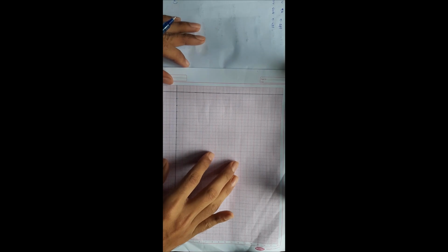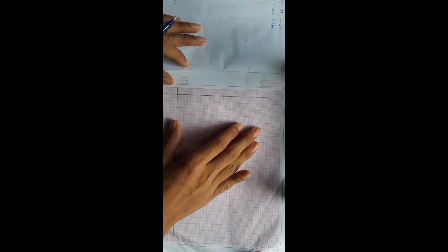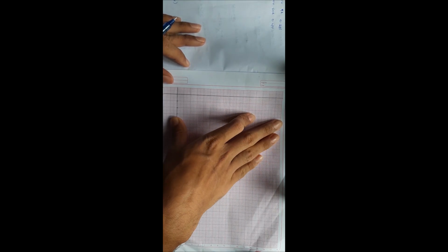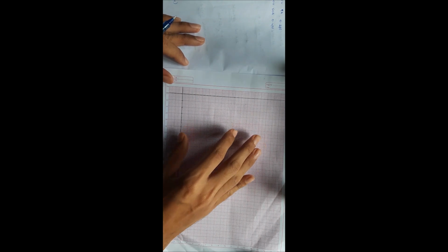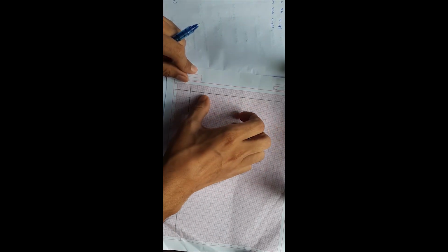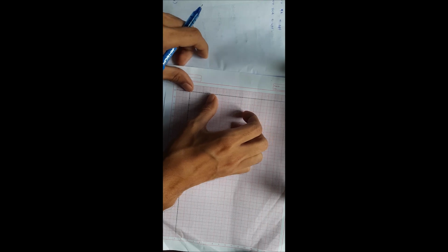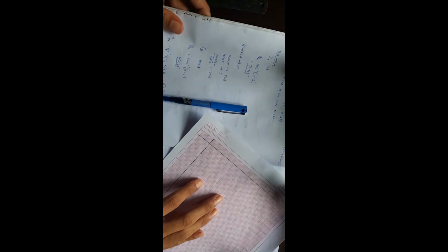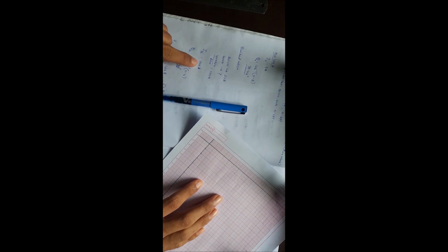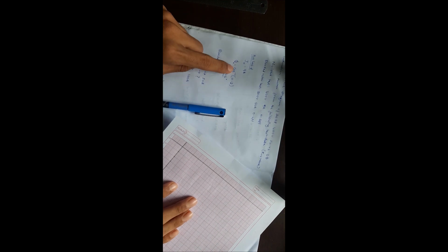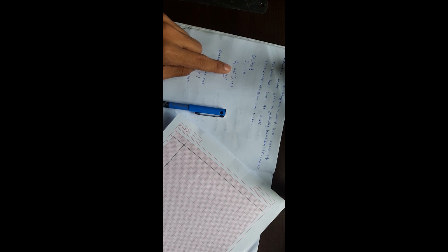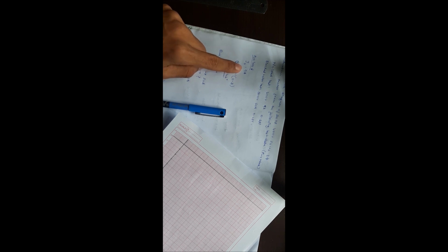After this initial calculation, we have to draw the no load and the blocked rotor current phasors. Here our y axis is the voltage axis and the x axis is the current axis. Since the current is 100 amps and almost 9 amps, we have to take a suitable scale.